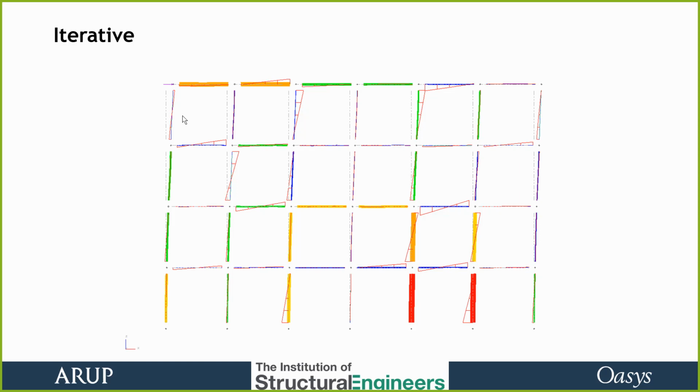The load path changes and all that sort of thing. So yeah, the initial sections can be crucial, but how do we avoid these problems? Well, we look at multiple load cases simultaneously, optimize them all at the same time. We can group sections together to make sure similar sections have similar sizes. If we've got wind from both directions, we make sure the structure is symmetrical, and various tricks like that to make sure you end up with a sensible final answer.